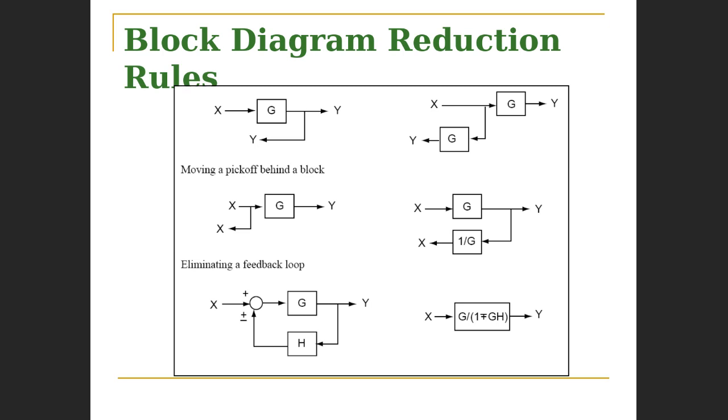That will become apparent in the next slide or next couple of slides, all right? But for now, I want us to understand and appreciate the rules that are presented here. These rules are like the rules that govern circuit analysis, and they're going to be important in simplifying complex block diagrams, okay? So we should be able to prove, or should I say you should recognize, that these two systems are equivalent. Yes. Clearly, we would see that when we pass y through this function, what we end up with is x, based on the fact that y is equal to x times g.